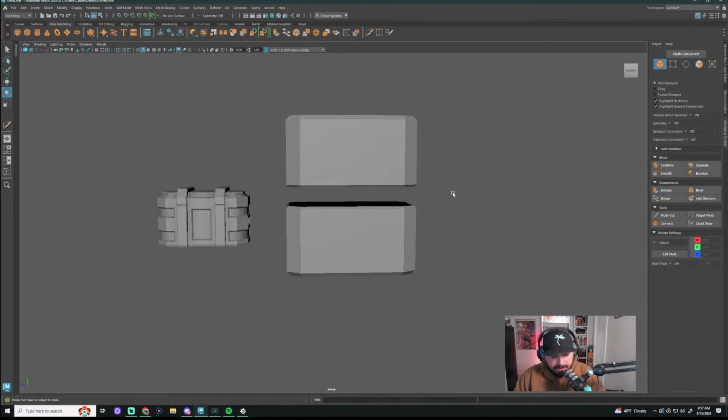Oh, it's because I was talking about n-gons. Yeah, some software doesn't play nice with them. Also causes problems with animations and deformations. Paul is 100% correct. They're a pain too because when you go to UV unwrap, sometimes they can cause problems with your direction of your unwrapping.